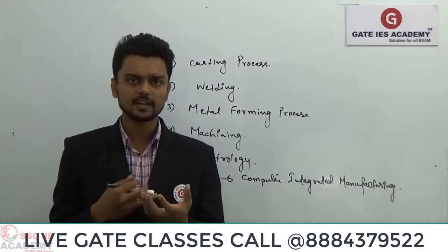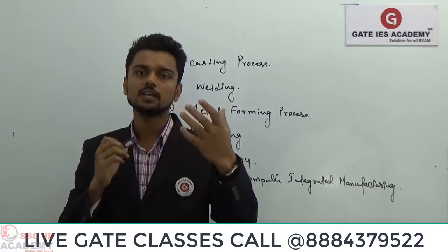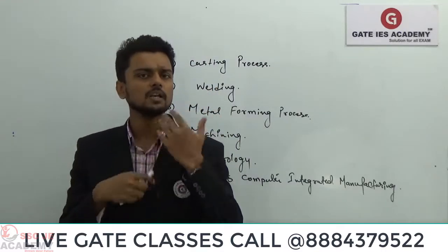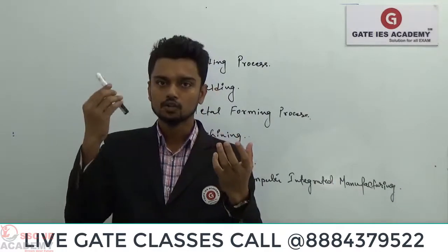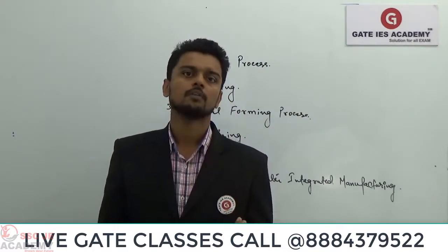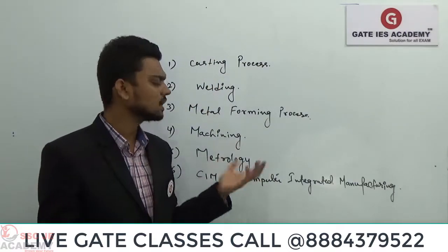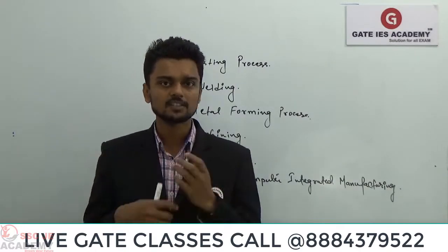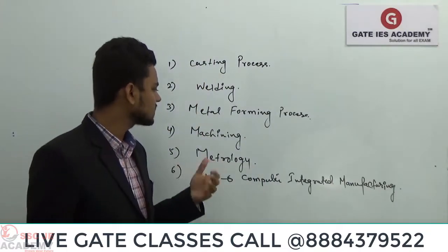How will we remove that material from the component? By using some kind of tool. Obviously the tool and the product should have some relative motion, then only we can remove the material. Also, to remove the material from the workpiece, the hardness of the tool material should be greater than the hardness of your raw material or the component. Then only you will be able to remove that material. So in machining, we'll discuss the different forces and the mechanism of chip formation, the mechanism of material removal from the workpiece. Then metrology is basically the science of measurement.